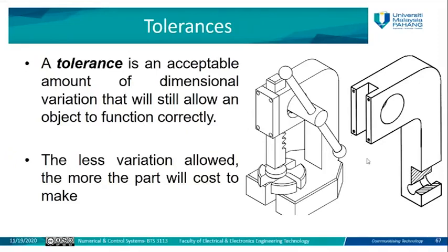The machine itself, either the milling machine or the drilling machine or the turning machine. It will make this error because it's a machine. A machine has mechanical parts, so there is vibration and rotation and so on. So it's not that stable, and there should be some type of error in the product. If this error is within the defined margin of the tolerance, it will be acceptable.